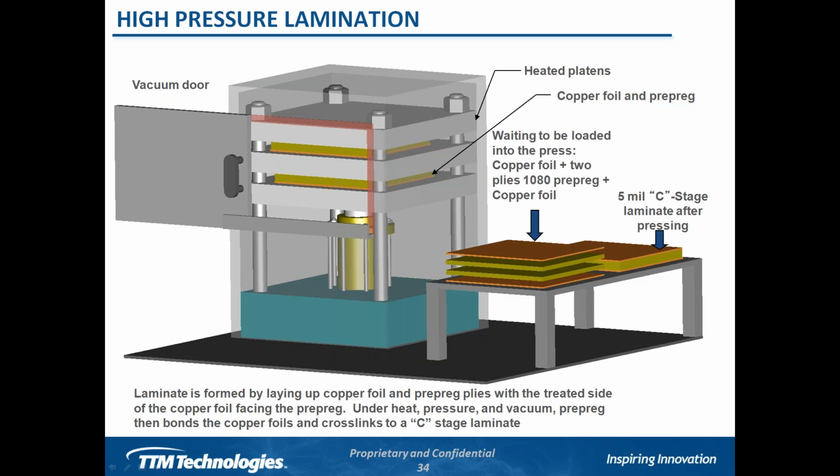However, depending on whether you need a sense of a safety factor in the design and you may ask for 2 plies, or whether you're trying to combat signal integrity issues, you may also ask for 2 plies. We do get customers that ask for 2-ply laminates as well. General rule of thumb for laminates, which I don't show here, is if you are at 8 mil laminate thickness or below, we're going to use a single ply laminate. And then once you're above 8 mil laminate thickness, all laminates are 2-ply.